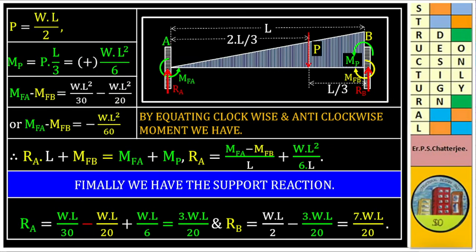Now we know MFA minus MFB is equal to W L square by 30 minus W L square by 20, or MFA minus MFB is equal to minus W L square by 60. By equating clockwise and anti-clockwise moments, we have RA into L plus MFB is equal to MFA plus MP. RA is equal to (MFA minus MFB) by L plus W L square by 6L.